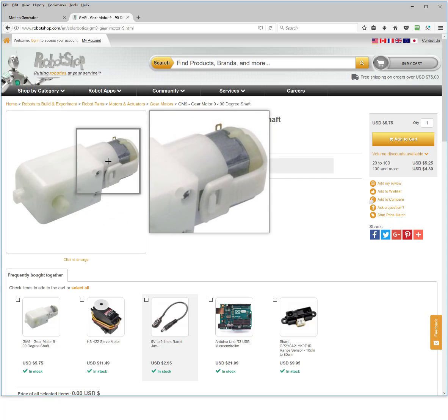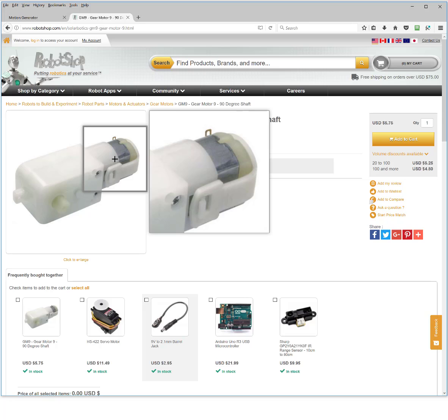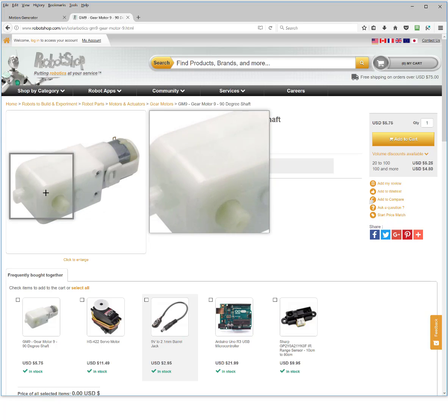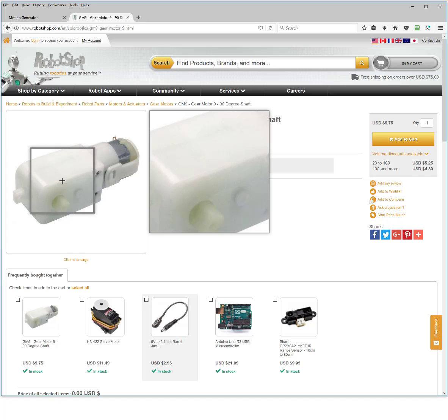This part you see over here is actually your regular toy DC motor that you saw, which was much smaller. This whole rectangular section that you see, if you ever open it up, you will find a two-stage compound gear train inside it. That's basically changing the speed. It's reducing the speed by almost a factor of 100 so that you can have 100 times the torque that you would need for high torque applications.